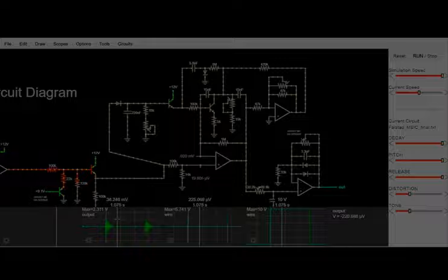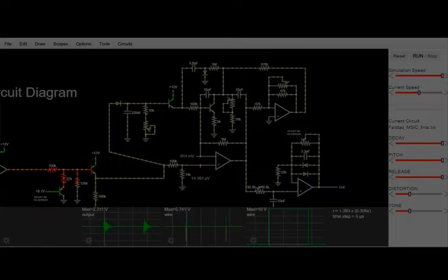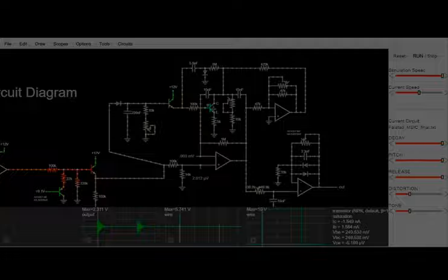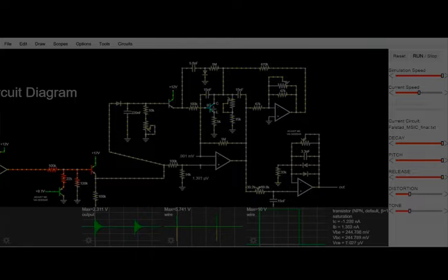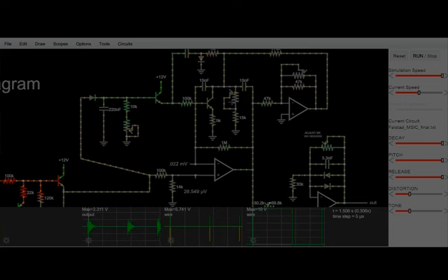Now, by carefully selecting the resistor and capacitor values, the oscillation frequency is kept around 50 to 100 Hz. Now, why is this important? Because if you talk about a kick drum, it has that deep bass. And to generate that deep bass, we need to touch frequencies of 100 Hz, 150 Hz, or even lower than that to achieve a very deep voice. So that is why we have chosen these values of resistors and capacitors.